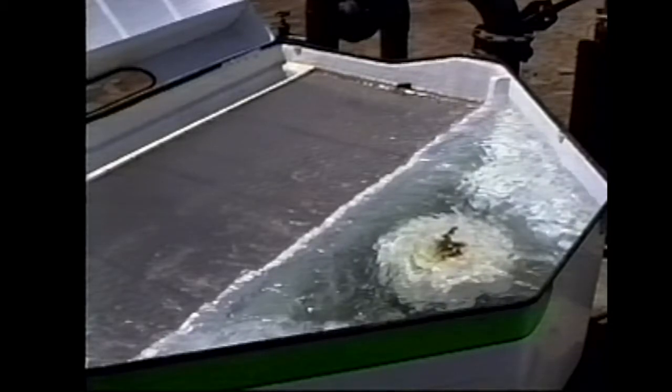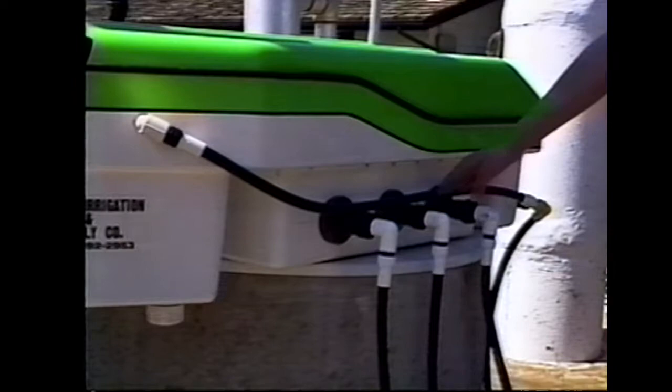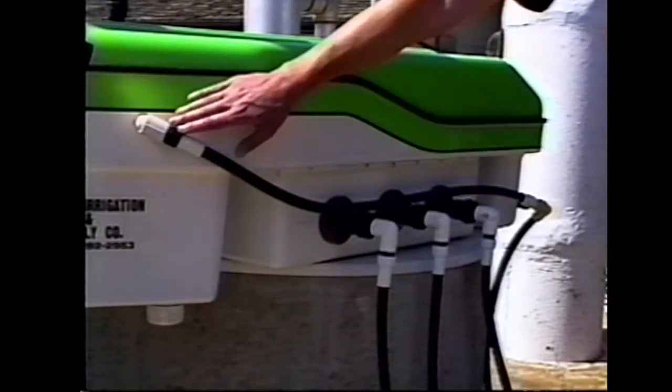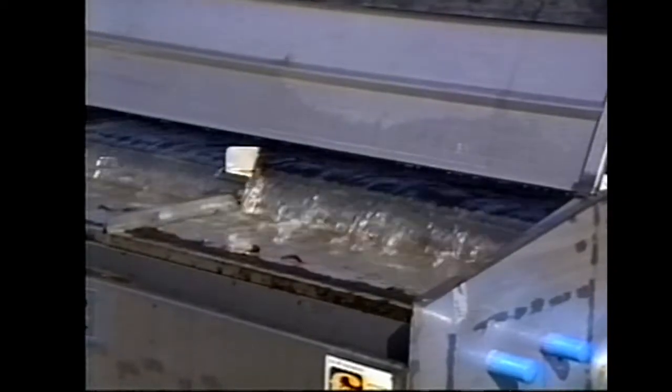This unit has a flow rate of 600 gallons per minute. Water, which also goes into the dirt collection chamber, is continuously removed using a venturi, which returns the water to the inflow section. The dirt must be manually removed from the screen and collection chamber about once per day. However, these systems have no backflush water to dispose of.